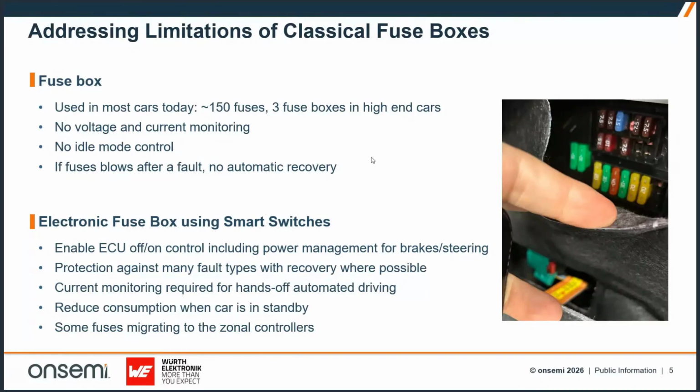And then you've got a failure, and all the power needs to go to the brakes and steering. You need smart power coordination to say, okay, turn off your speaker system, we don't want that. Turn off the heating, that's not necessary. Sorry about the seat heating, that goes off as well. All the power then gets reserved for the brakes and steering. That's really important. That's a key development.